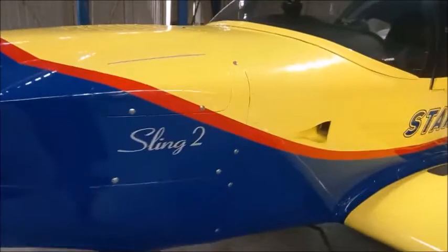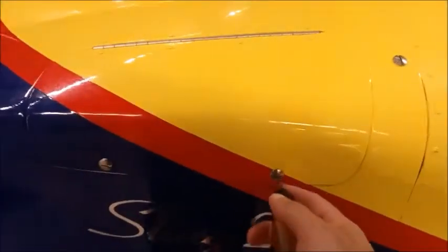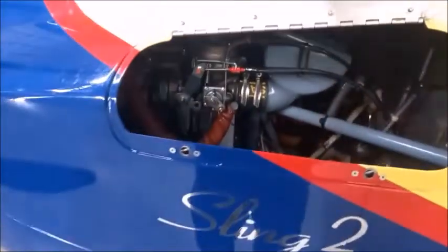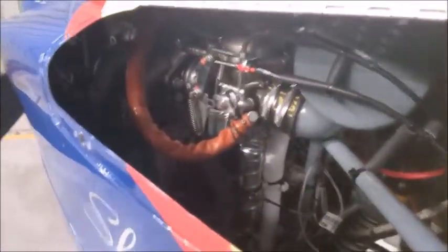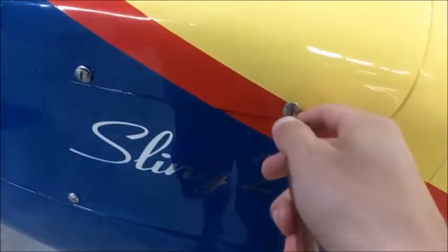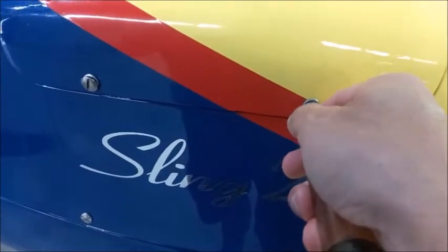Okay, let's start over here with the engine and start doing inspections. We open up the engine compartment. This is a 4-stroke, carbureted engine, and what we do is we try and see if there's anything that might be inside of it, like an animal that built a nest, or had babies during the night. This often happens especially with cats or rodents. Make sure that there's no cables that have been chewed off. Click and then close the engine compartment.